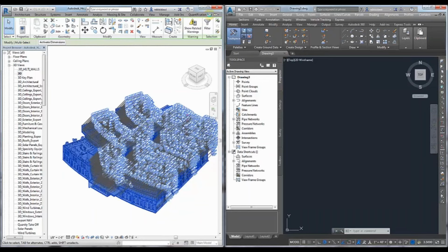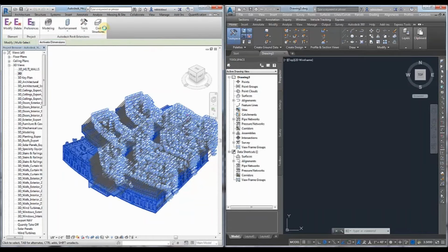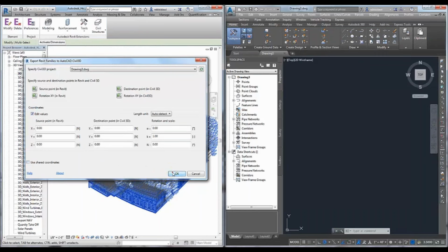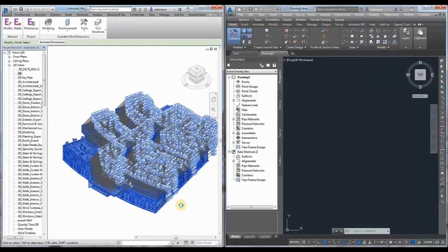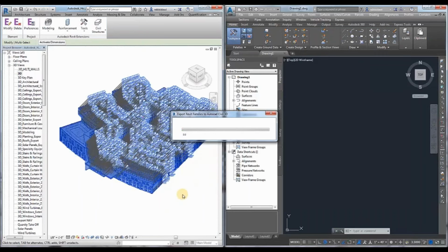Usually the civil engineer will have some type of site coordinates that they go by, and it could be very, very far from the project. You want to avoid that because Revit has a limit on the extent of the project. If it goes beyond 20 miles, then it will give you an error message, or maybe your project components will be inaccurate. So avoid creating a project in Revit that's greater than 20 miles